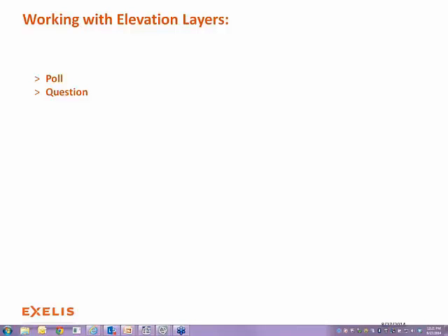Yeah, great question. Thanks. I actually just put together a couple of screen caps for a customer who was asking me that just this week. What ended up working really well to do some pipeline extraction analysis from elevation information was to look at that height model, the surface elevation minus the bare earth, and use the feature extraction with 2 passes to pull out an above-ground pipeline feature, remove the noise, and then actually extract the pipeline and its elevation along there.